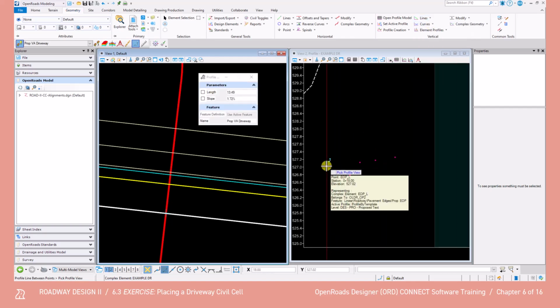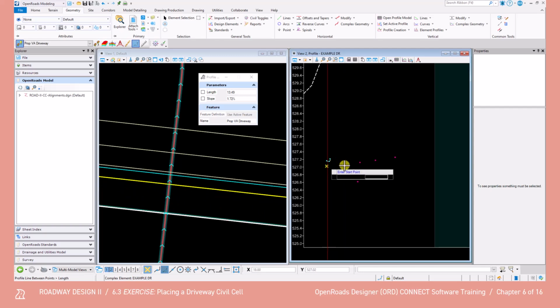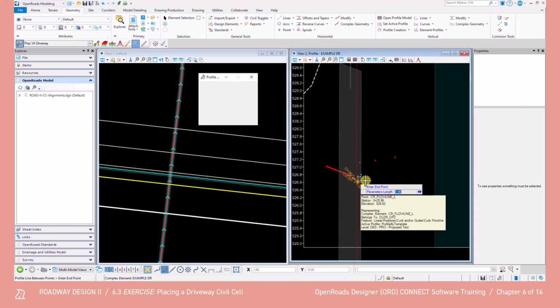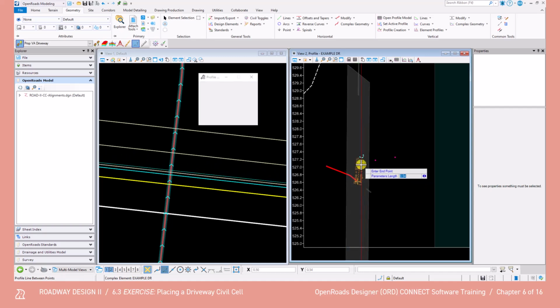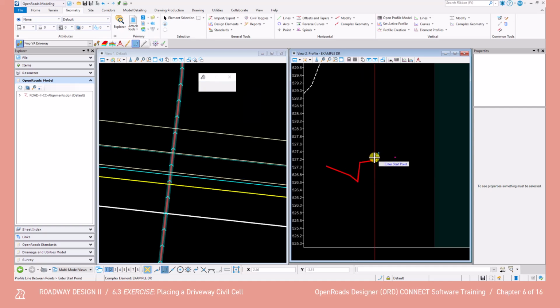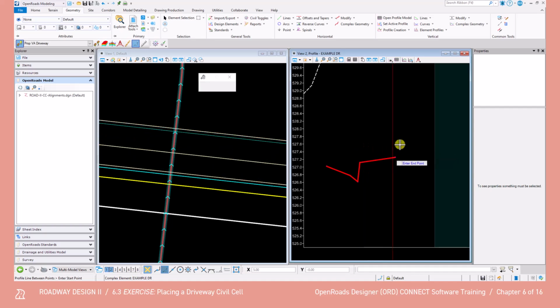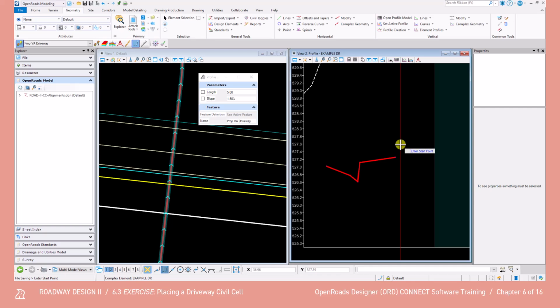Then from the SW back top L intersection point, we're going to draw 3 more tangent lines. This first tangent extension will keep the vertical curve outside the project limits of the sidewalk. So this first line will go from this SW back top L point and go for 15 feet at a slope of 1.5%.